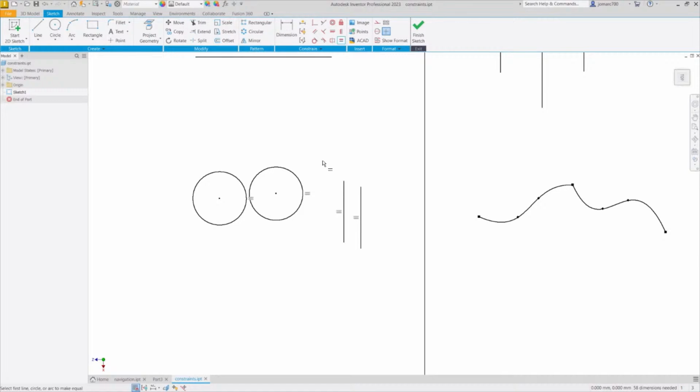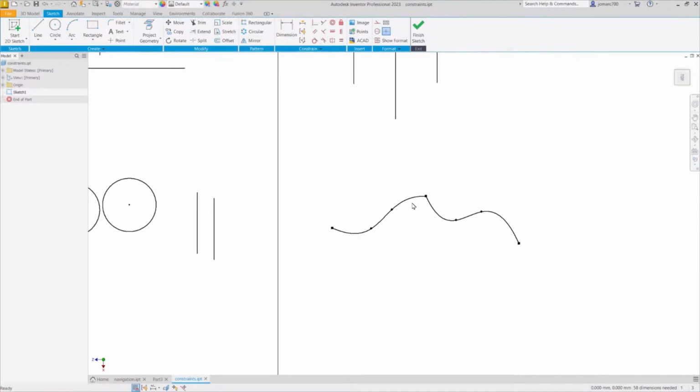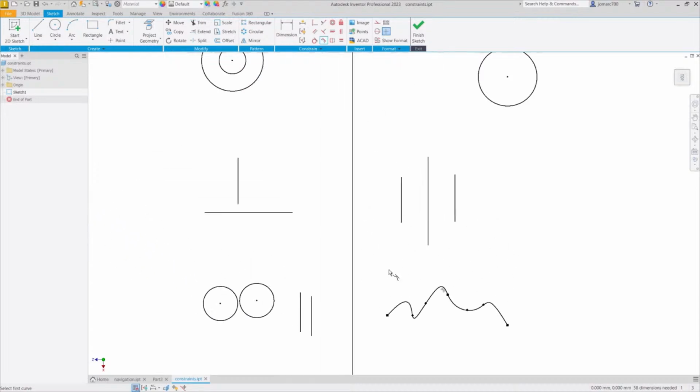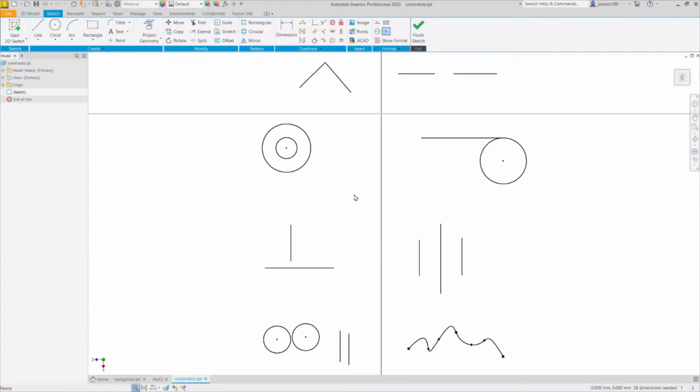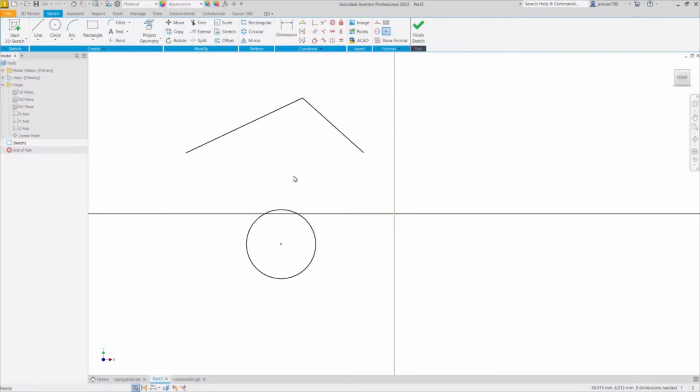And finally, let's discover smooth. In this instance, I have two splines, and I would like this point to have a smooth G2 transition. Selecting smooth, selecting this spline and this spline. So notice the smooth transition in effect at these two splines. Double click on our mouse wheel to zoom extents. Hitting escape. And from here, let's reiterate the applications of these constraints to our unsaved file.